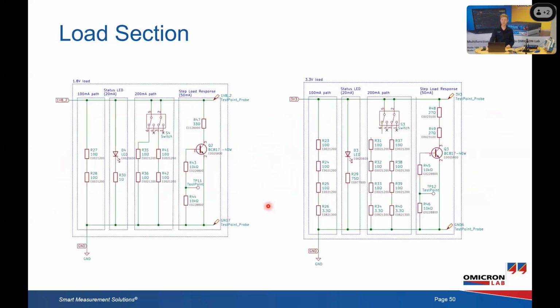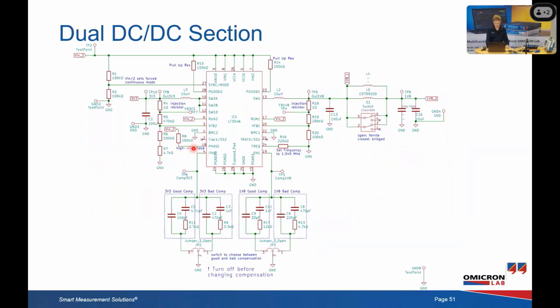And then we have the load, which is just causing some resistive load. Also a small transistor to do some load stepping so that I can show transient response on the oscilloscope. And the converter itself is a chip that has the switches inside. So we just have the output filter, we have the storage inductor, we have the output capacitor, a ferrite bead and a second decoupling capacitor. And then we have the feedback divider here, 200 kilo ohms and 100 kilo ohms.